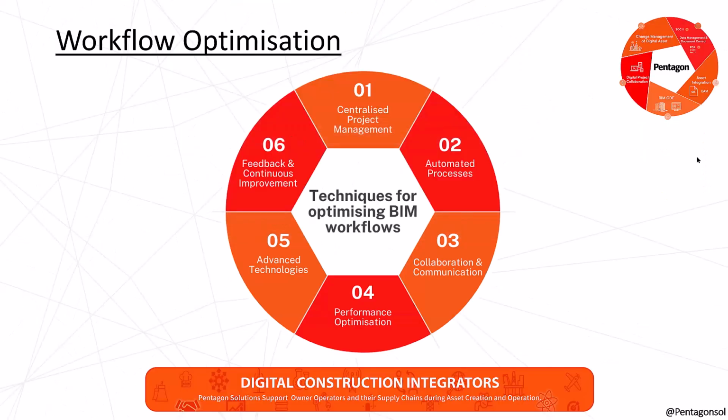So I'm going to take you through a few of my favorite optimization techniques for your workflows that you can bring on. This will significantly increase efficiency, collaboration, and overall quality of the construction projects. So firstly, the use of a CDE to store and manage all project information in a single location. This ensures all stakeholders have access to the latest data, as well as they're able to leverage cloud-based BIM platforms to facilitate real-time collaboration and data sharing. This then reduces delays caused by information silos.